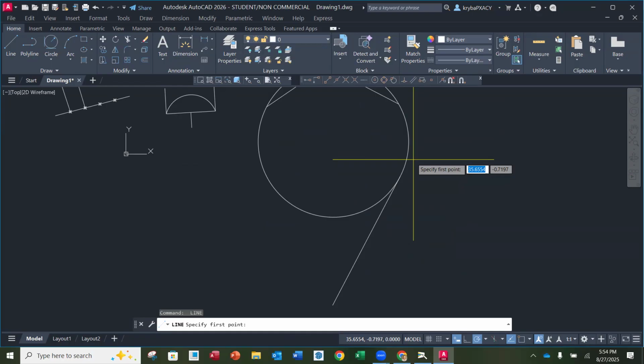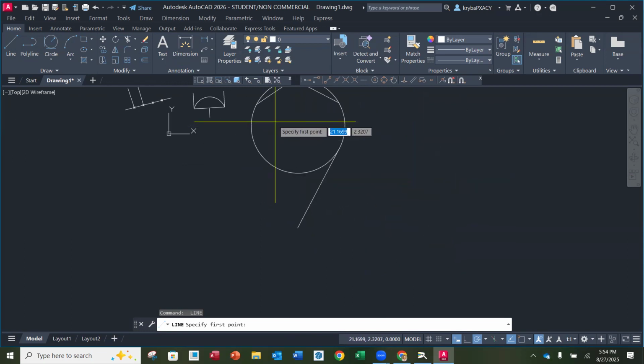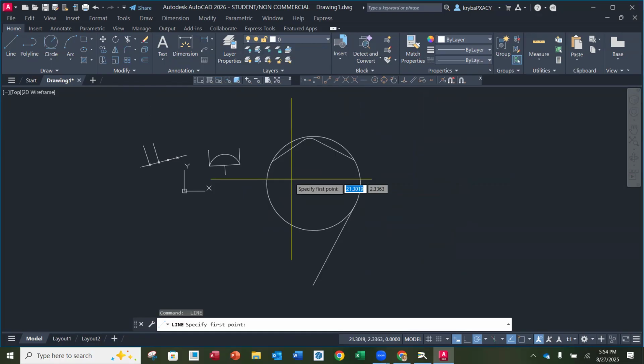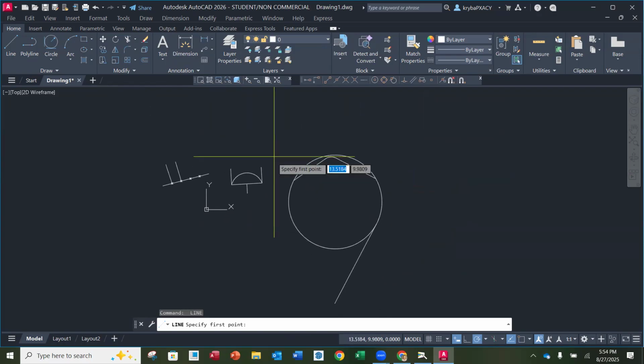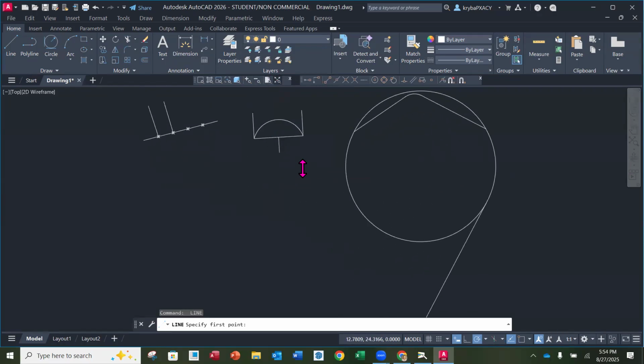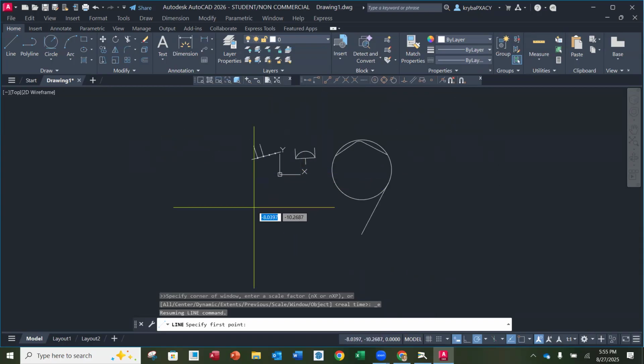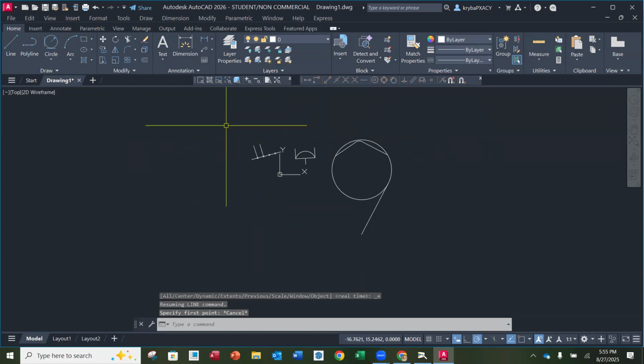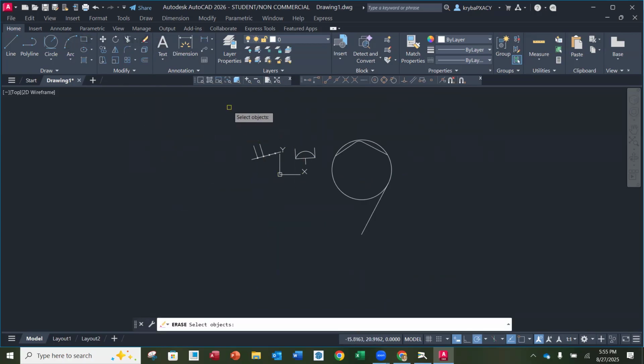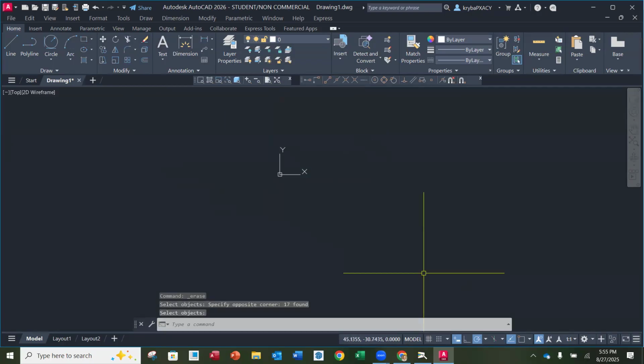All right, so now we are ready for the gasket design. Before we do the gasket, I'm going to get rid of everything on my screen, and I'm going to zoom out a little bit with my roller, and maybe pan a bit, or you can do a zoom extents. Then right in the middle here, you can roller towards yourself a couple times to get it smaller. I'm going to hit escape. I'm going to use the erase command, left click, right click, and then enter to get rid of everything. This tutorial is in inches, so we already started in imperial, so we should be good.